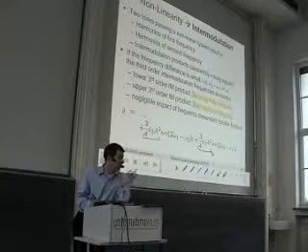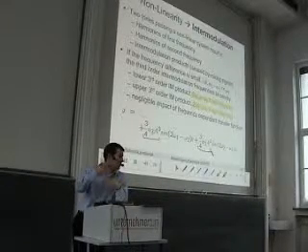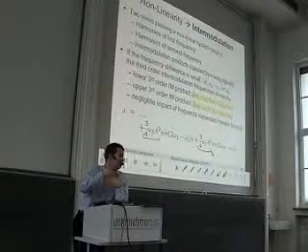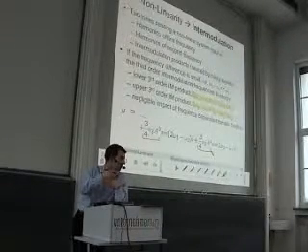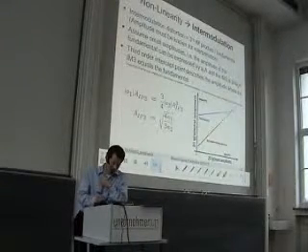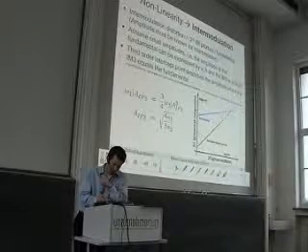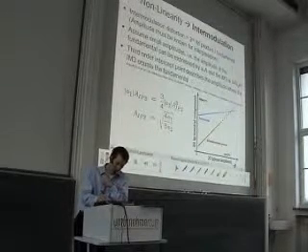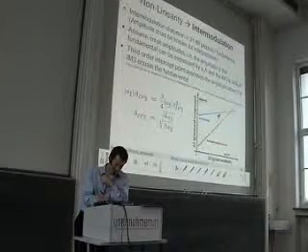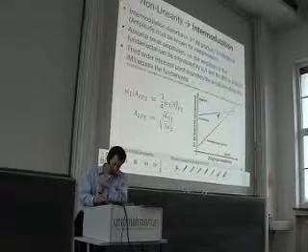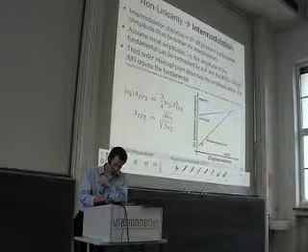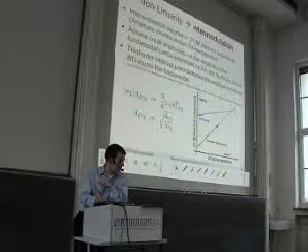If you go back to the slide with all these equations, then you see the fundamentals scale with the first power of the amplitude. Hence, if you have a plot where you increase the amplitude from low values to high values, the fundamental goes up with A. The third order intermodulation products go up with A to the power of 3.